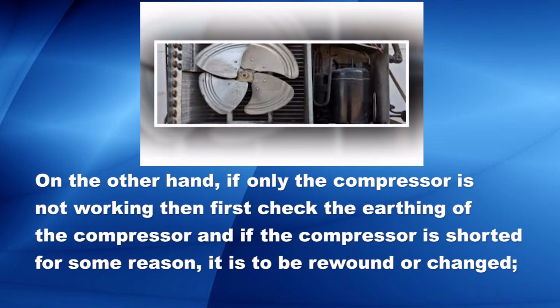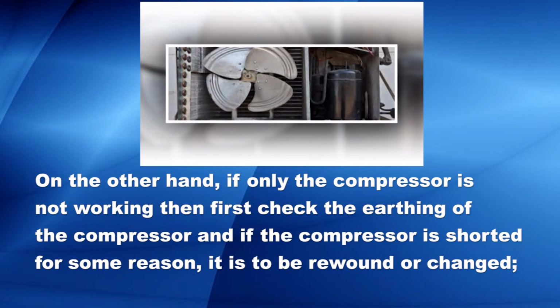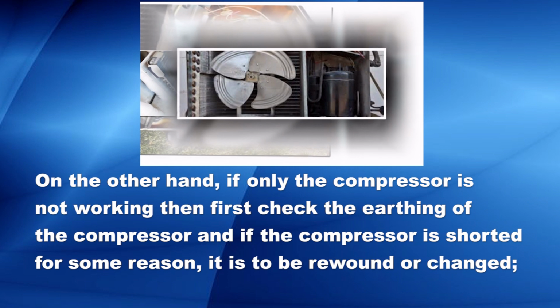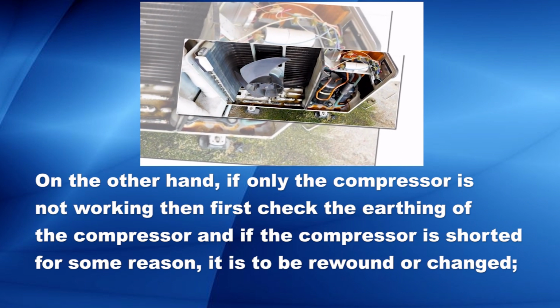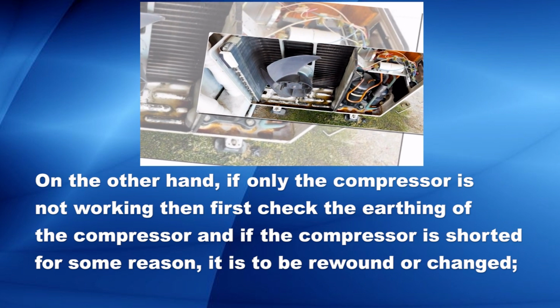to be rewound. On the other hand, if only the compressor is not working, then first check the earthing of the compressor, and if the compressor is shorted for some reasons, it is to be rewound or changed. Next you have to check the capacitor of the compressor and the overload protector. If any of these are found to be defective, then change it. Thereafter you should check the thermostat temperature setting and adjust it if it is not properly set.